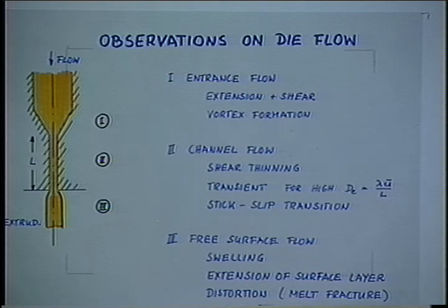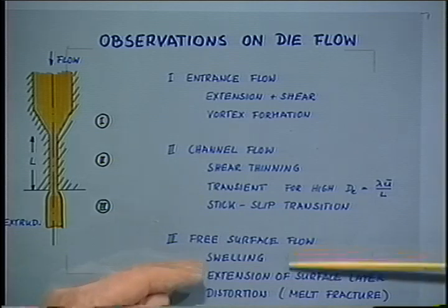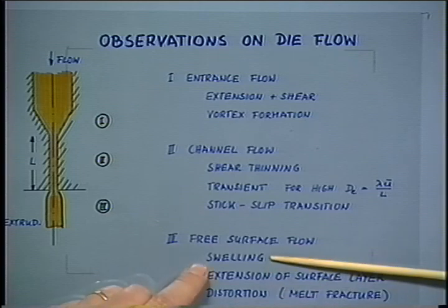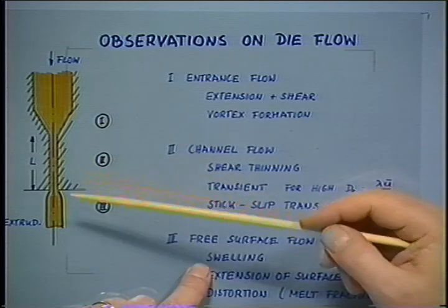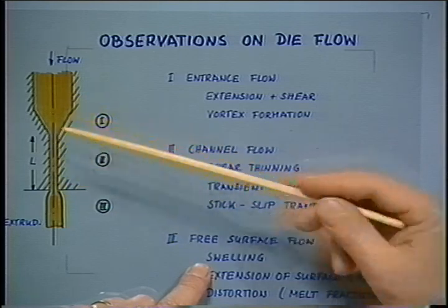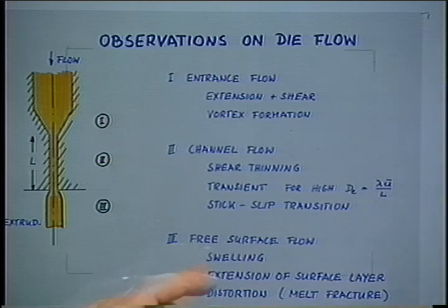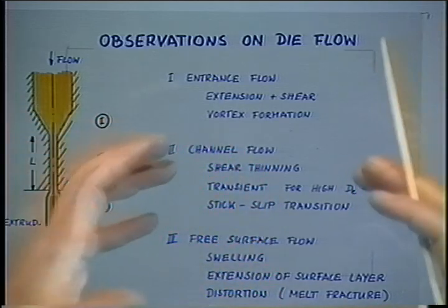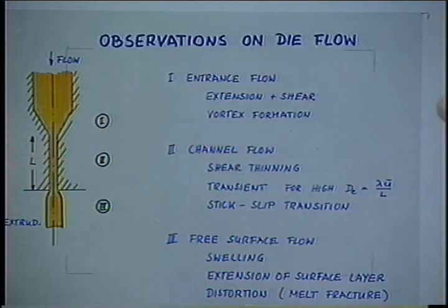Now, that's the interesting observation. Let me jump to the free surface flow since I started talking about swelling. Even if this capillary is very, very long, so the material clearly doesn't remember that it was stretched when it entered the capillary, even then, the material swells at the exit. It swells, and the diameter is 2 or 2.5 or 3 times as big as the diameter of the capillary. It's a very large phenomenon.